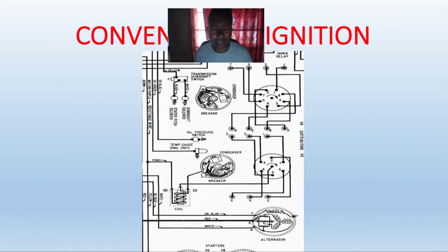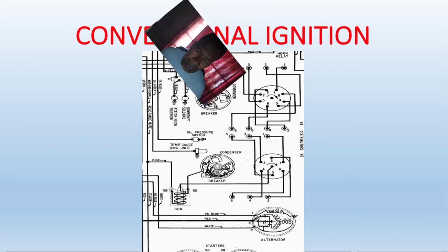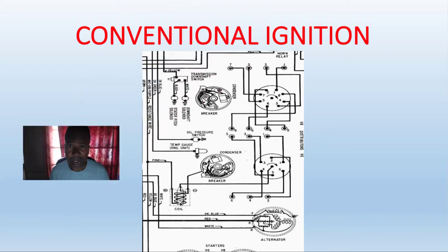That's another way to look at it. We have power here, a coil, the negative side again, so you see positive, negative. And look, this is an old school distributor breaker point system. You can see the points right here, the contacts right there. And here's the distributor cap.